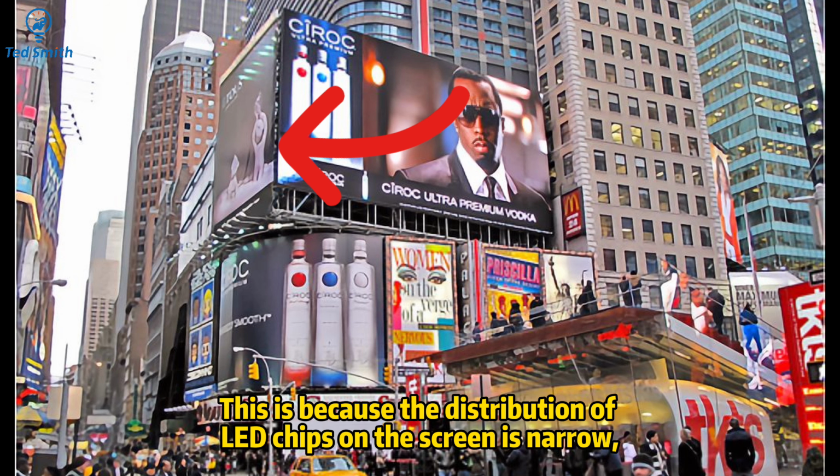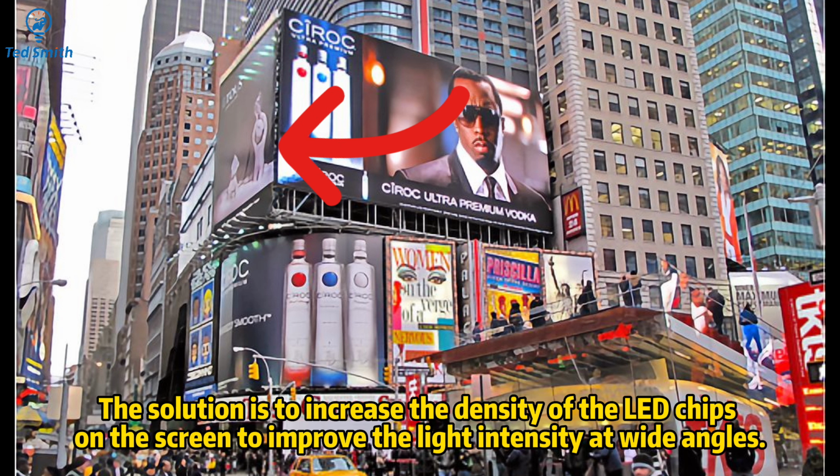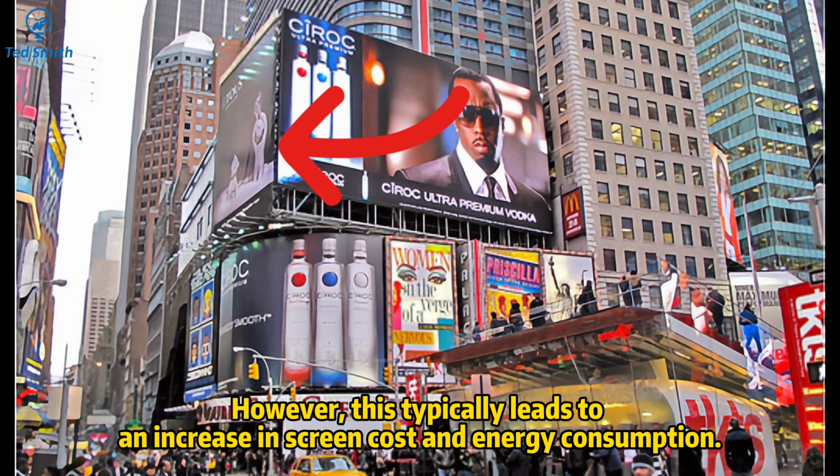This is because the distribution of LED chips on the screen is narrow, which results in insufficient clarity at wide viewing angles. The solution is to increase the density of the LED chips on the screen to improve the light intensity at wide angles. However, this typically leads to an increase in screen cost and energy consumption.